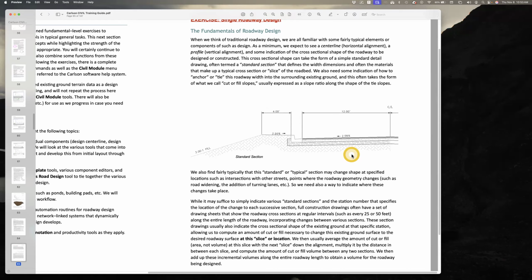If you think about a roadway, let's say the access road, the driveway into a site, like an industrial site, and you think of designing that roadway from the perspective of a site development or site design engineer, the site guys might consider constructing this site from the subgrade excavated area, with a certain thickness of certain materials, and they build the site up till they reach the top surface. So it's basically a vertical design approach.